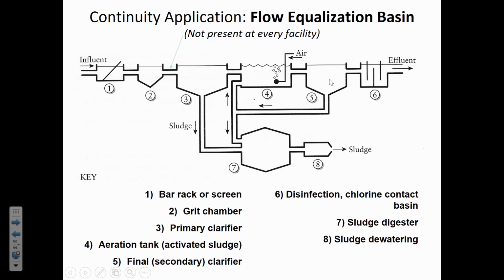And so what you'd do is you'd pump sludge from the bottom of a clarifier and you'd put it into an aeration basin, and so then that would begin to remove the dissolved solids as well as the ones that were just suspended. But one of the tricks of doing that is that the bugs that are living in the secondary reactor require a pretty steady flow of air and food. Microorganisms can't just be turned on and off like a switch. It's not like a pump where you can just push a button and then the pump is operational. The microorganisms take days and in some cases weeks to become fully established and to colonize a wastewater treatment plant.